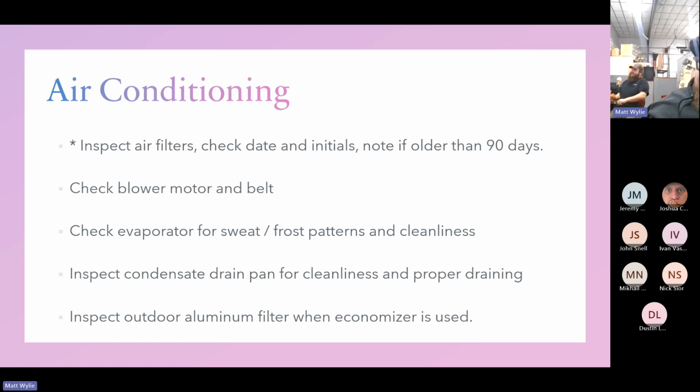Defrost block on everything. It gets the job done until someone goes behind you and tells your customer, whoever did this is an idiot. And then we look bad. I love being the person to go to the customer and say, I don't know who you guys were using before us, but rather than doing this, they threw a time clock on here. They probably charged you $500. And if you ever feel like it gets hot at random points in the day, it's because your AC unit that's not supposed to be below freezing is in defrost. Oh, it was you guys.